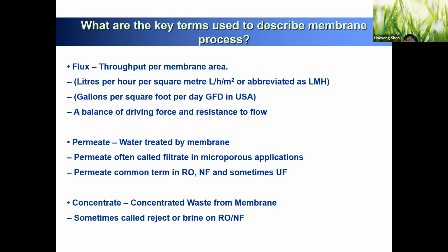So how much membrane surface area, how much pressure you have to apply, and how many membrane modules or elements you need for your desalination plant design for 250 megaliters per day. So that's your second question of assignment 3: design your banks, how many elements you need, how much surface area you need, how many modules you need. That's the question you have to answer for your scenario.